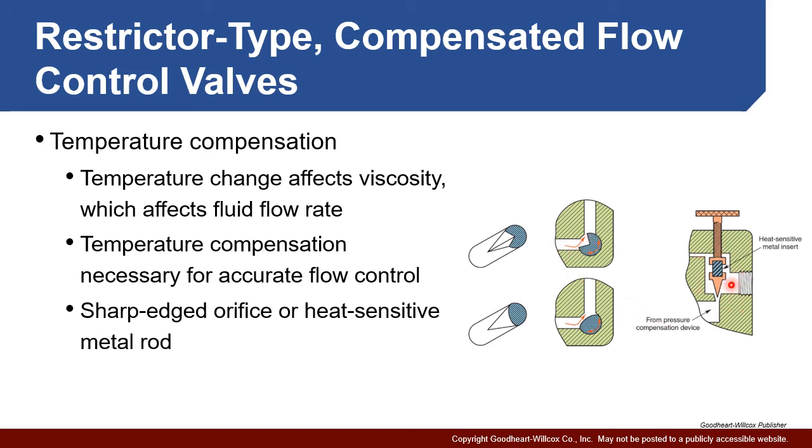Another solution is to take advantage of thermal expansion. As we know, when things get hot, they get bigger. As they get cold, they get smaller, and you can build in a heat-sensitive material. As it gets hot, it actually tends to close the valve. As it cools off, it tends to open the valve, so it compensates for the change in viscosity. So a couple of different mechanisms can be used for this. Keep in mind, however, when we're dealing with hydraulic systems, we do want our temperature to remain relatively stable. So this would be only in situations where we weren't able to maintain a stable temperature.